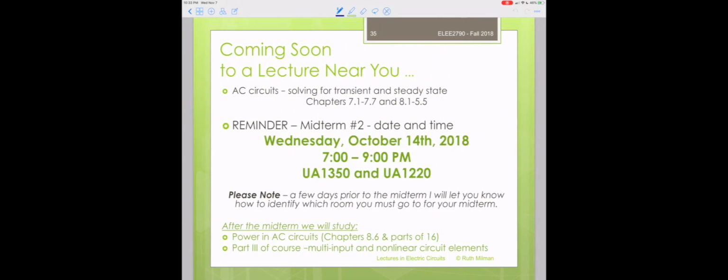Solving for the constants in the first order solution system is reasonably easy because we just have to look at the equations directly. As you saw, when you get to higher order circuits, it becomes harder and harder because you have to start looking at the different values of the higher order derivatives in order to get the initial conditions for all of the pieces that you need. So it can be a little bit cumbersome, it's harder to do, but as a process, it's a straightforward process.